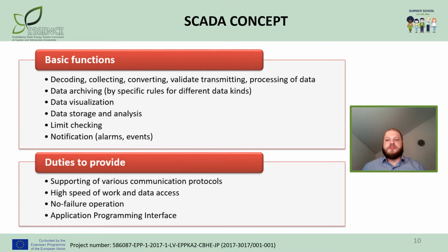Some sensors measure more complex situations where exact measurement is important, like power flow, energy output, solar irradiation, whatever. These are analog sensors, which can detect continuous changes in a voltage or a current input, for instance. Analog sensors are used to track voltage levels, temperature, and other factors that can be measured in a continuous range of input.